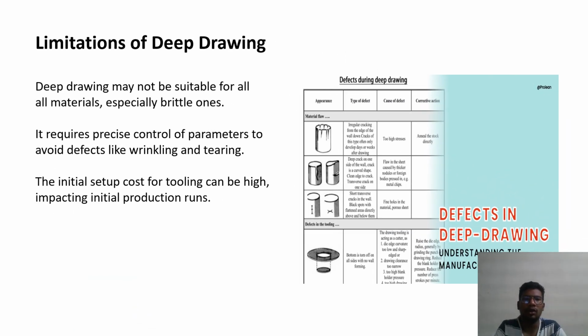Limitations of deep drawing. Deep drawing may not be suitable for all materials, especially brittle ones. It requires precise control of parameters to avoid difficulties like wrinkling and tearing.